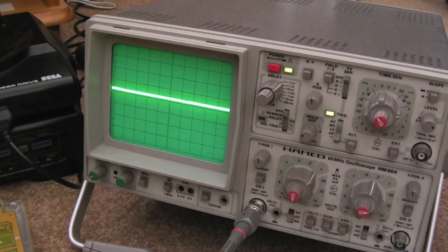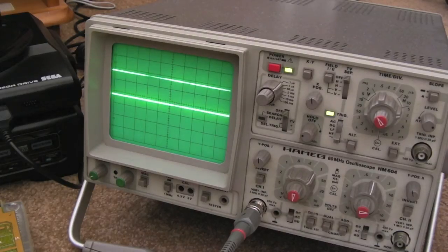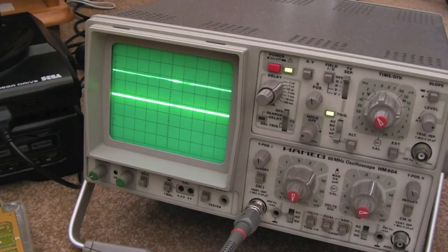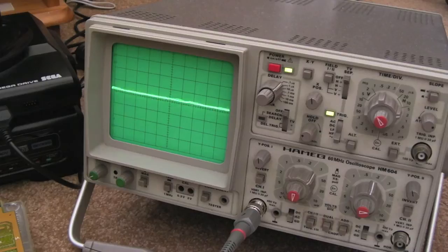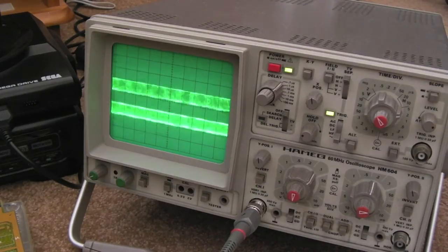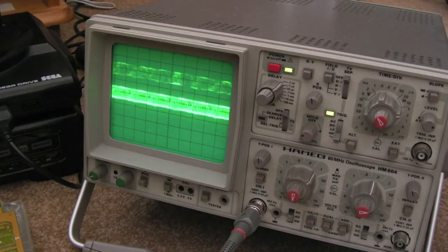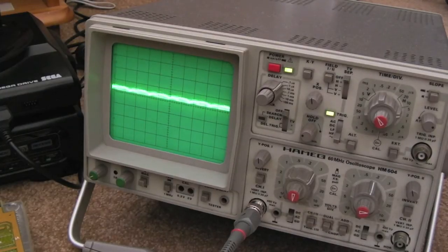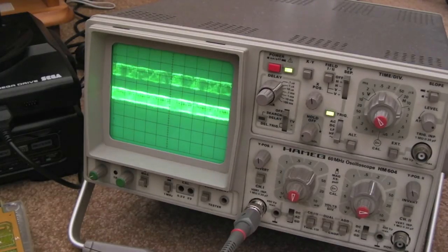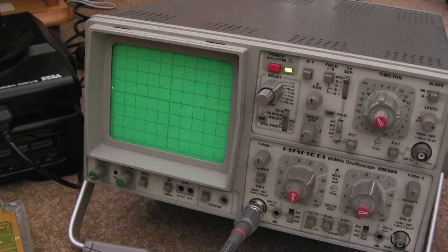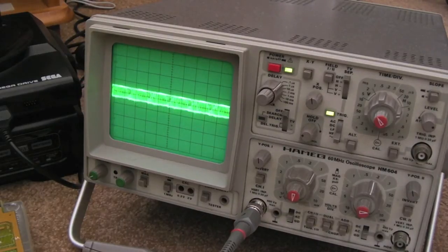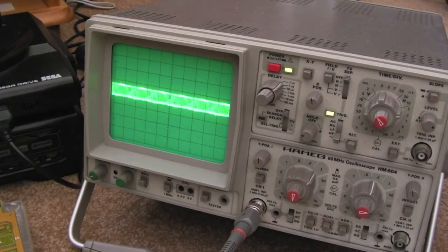Now bear in mind that these will be connected to the same data pins, so it's hard to determine from this which of these two chips is faulty. But as I'm going along the pins here, you can see one's okay, one's not, one's okay, that's really strange, that one. That might even be the chip that's faulty because that's given a really unusual reading. Yeah, this chip is looking very odd. I think this might be the one. I'm going to change this. This is the one I'm going to do first, which is the V4 chip on this board.